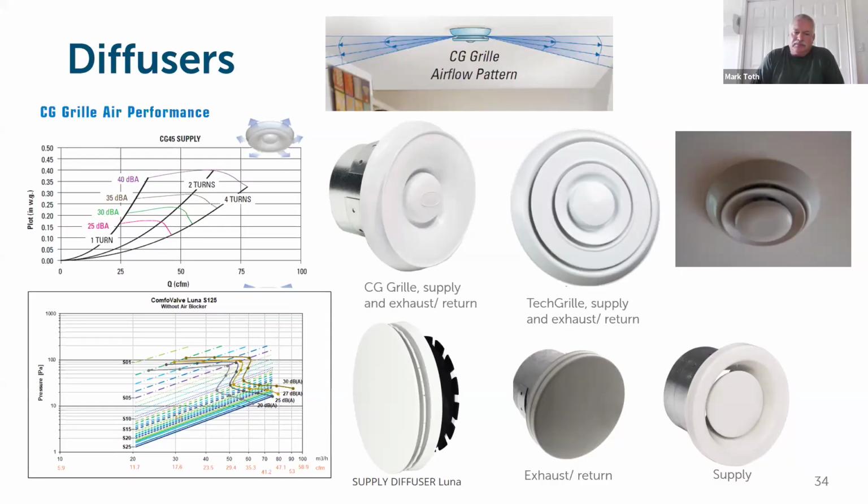Right, good point. So for diffusers, these are some options that I like that do that sort of bending or deflecting of the air, like pushing it against the wall or the ceiling rather than onto people. They're adjustable, very simple to install, and pretty cost effective. They come in all different shapes, sizes, and materials. Usually the plastics work better for adjusting than the metal, since metal on metal isn't going to seal very well. And look for something that has a good profile of the air distribution, so you know it's going to provide comfort.